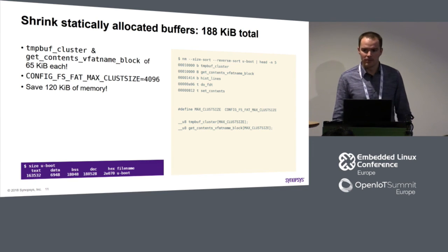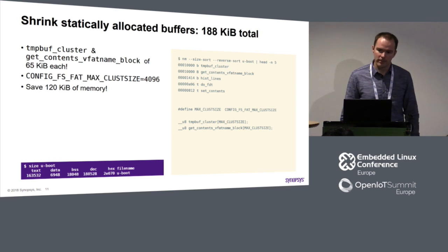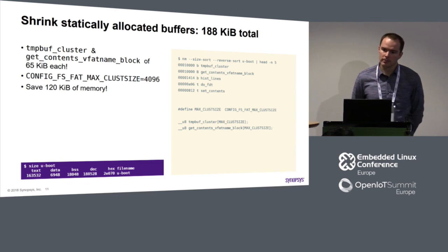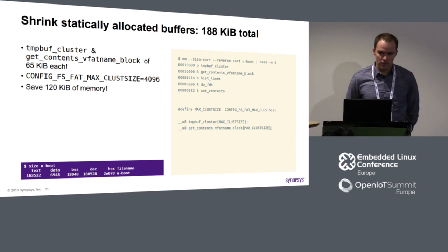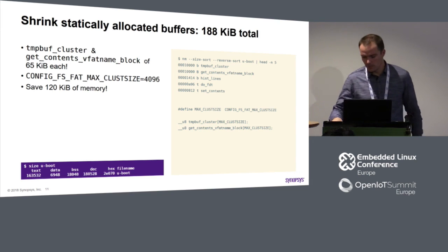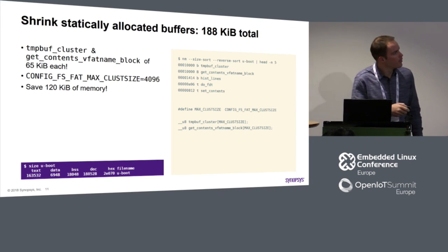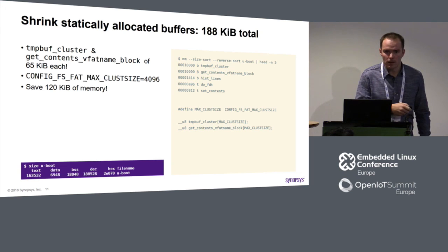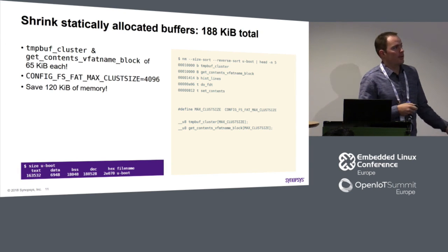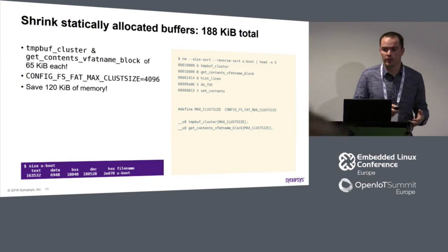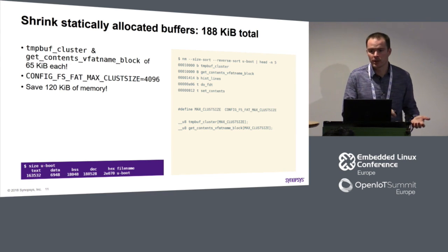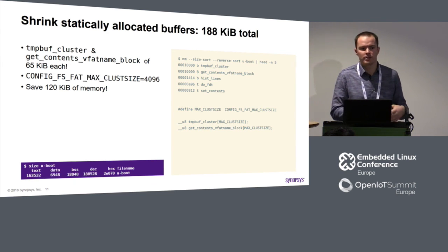The framework-related stuff as well, where you create each symbol in a different section, and then at link time you realize which symbols are not being referenced anywhere, and then you strip them off. I would guess that will be at somewhat more of a framework level rather than your platform port. Yeah, as I said, it should be a generic feature, but probably back in the day it was not supported. I know that for ARC it was not supported a couple of years ago, and then it became supported.